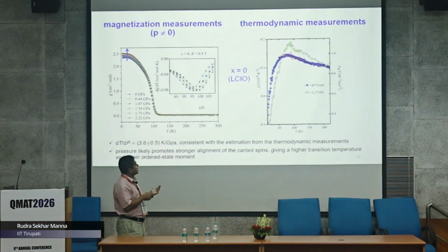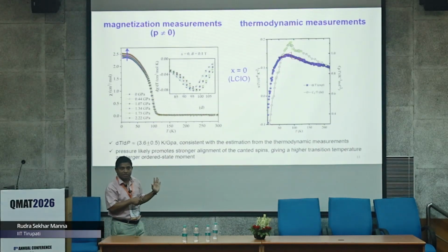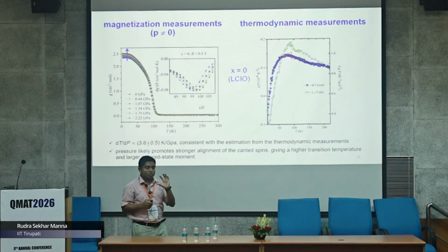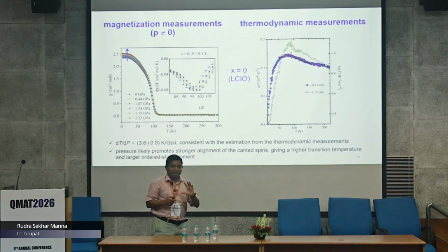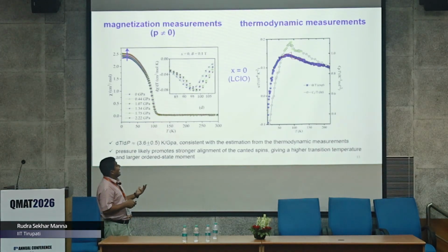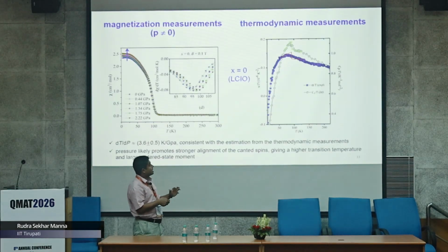So you can measure a parameter called thermal expansion, the expansivity. That means you take a sample, you apply some temperature, then it usually contracts or expands, and from there you can calculate the thermal expansion coefficient. Then you can also do heat capacity, the specific heat measurements, where you give a heat pulse and then measure the temperature.